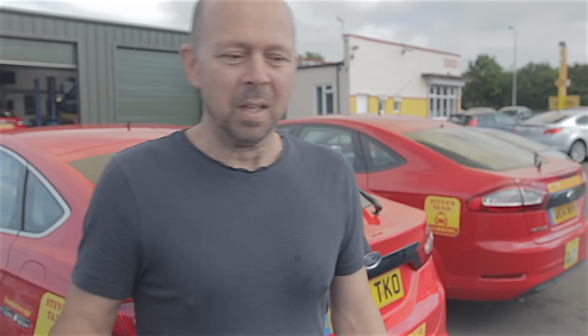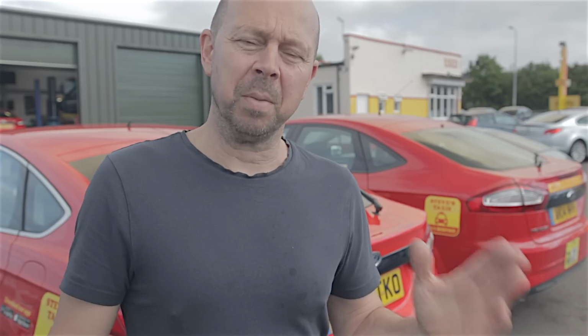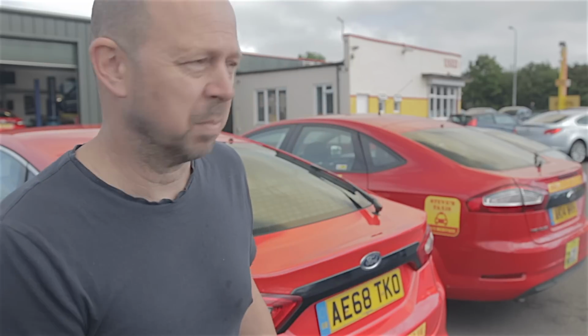So a little while ago, I went into this and tried to find the problem, and as I was looking up the side of the heater box on the driver's side, there's a motor up there and there's another motor on the passenger side. I found that the motor on the passenger side of the dash, on the heater box, controls your distribution from the screen to the vents and to the ground, whereas the driver's side motor does your hot and cold, your heat distribution, so to speak. But I never actually got to changing the motor.